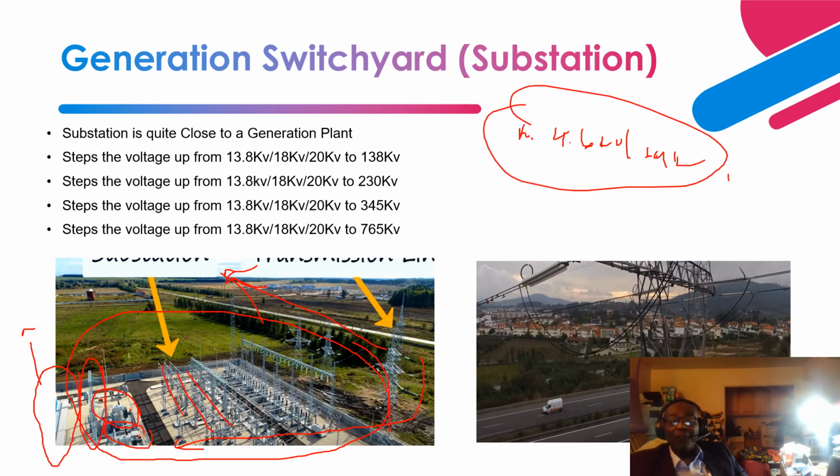So let's say you have a 115 kV coming in from a transmission network, right? That basically goes through a transformer that steps it down to 4.16 kV or 6.9 kV before it is fed to a medium voltage switchgear with this level of rating, right? And this medium voltage switchgear is what feeds power to all your auxiliary equipment.